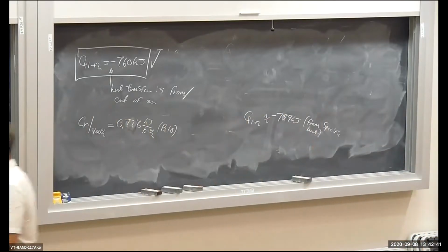Is it 33 or 37 bar or something like that? 37 bar. Our maximum pressure is going to be P1, which is 2.5 bar, so we're definitely below 0.2 reduced pressure. So ideal gas behavior, you can check it, it is valid.